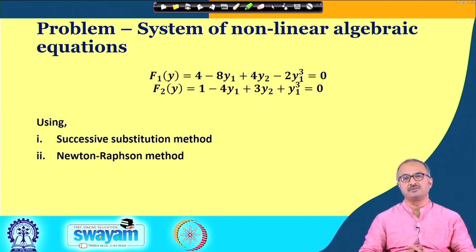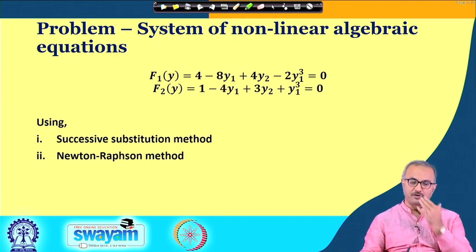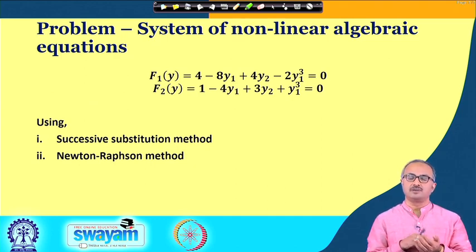What happens in those cases is that you write the balance equations for momentum transfer, mass transfer, and heat transfer, and then you find that all these equations become coupled, because for example, in the heat transfer you will find the velocity is coming, and the velocity is obtained from the momentum transfer.